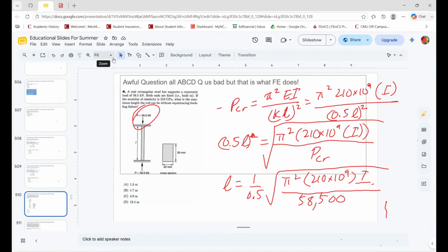It is a steel bar, so you can imagine what the base is. The base is 20. No, the base is not 20. It's not 20. So it's bending this way. Again, what a tricky one this is. The base is actually 30 by 20 cubed divided by 12, because for a bend, it's the longer side that's the base. I don't like how the question set it up. Again, they should be more mindful, in my opinion, of how they showcase the problem, but they won't do that because we're engineers and you're supposed to be able to do whatever calculation is given by just looking at something.